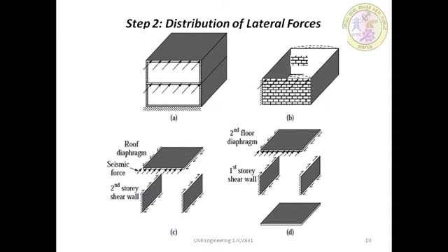Whatever the lateral loads are, they are transmitted from these transverse walls to the side shear walls by horizontal floor and roof diaphragms. The diaphragms distribute these forces to the vertical resisting components such as shear walls and other vertical resisting elements, if any, which then transfer the force into the foundation. The diaphragms must have adequate stiffness and strength to transmit these forces.